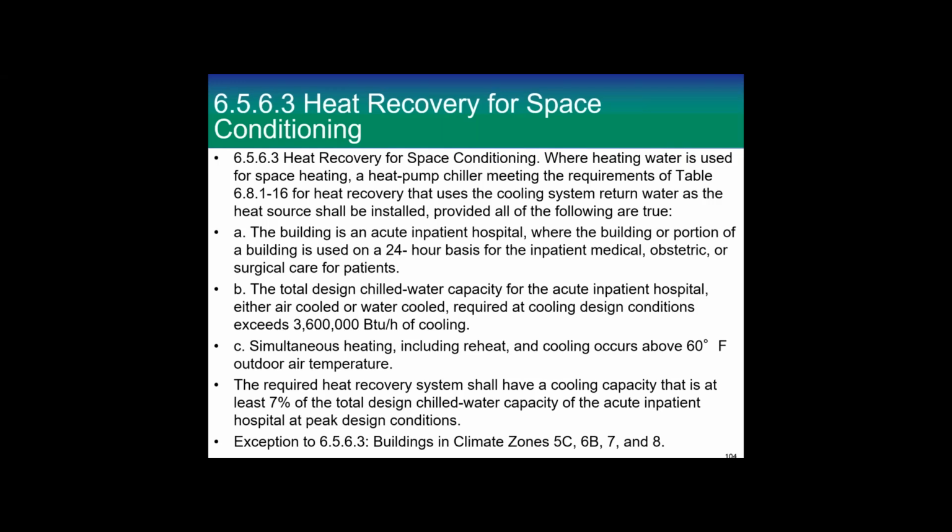Heat recovery for space conditioning. So we've always had some heat recovery for water heating, and that was in hospitals and prisons and stuff. But this is heat recovery for space heating. So a heat pump chiller meeting the requirements of tables 6.8.1.6, which is just the efficiency tables, for heat recovery that uses the cooling system return water as the heat source shall be installed, providing all the following are true.